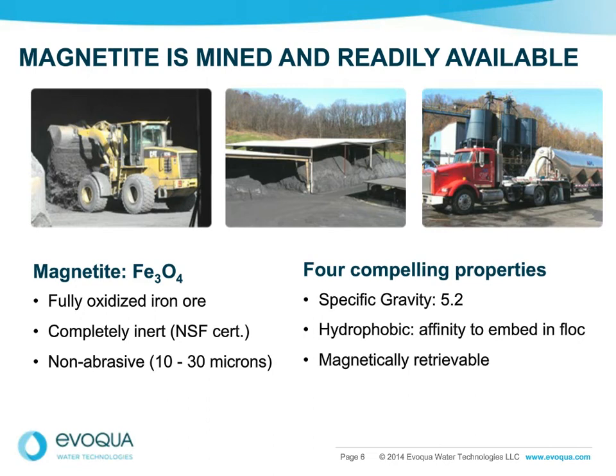And the way we recover it is we take advantage of it being fully oxidized iron and use a magnetic field, and Kevin will explain the process of recovery later on in this webinar, and recapture the magnetite and put it back in the process again. So you're essentially just disposing of the generated biological solids or chemical solids.